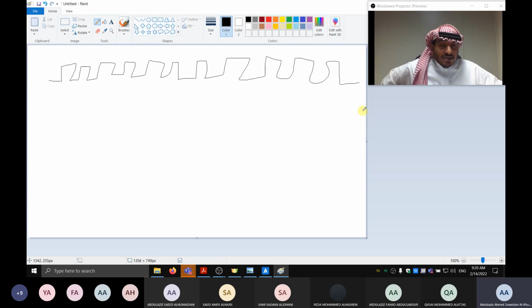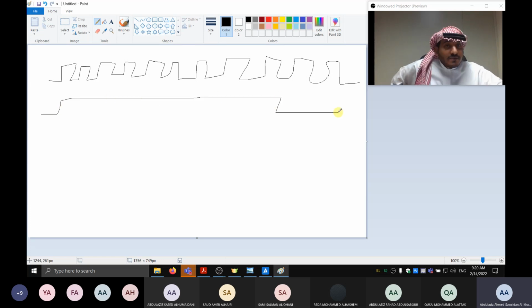So now that's a clock signal, and you pressed a button to count up once. When you press a button, it's like this. That's only one press. You see, at 50 megahertz the time period is very small. So when you press the button, what does the system see?